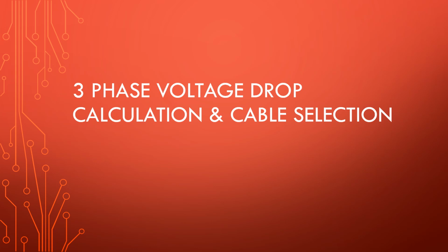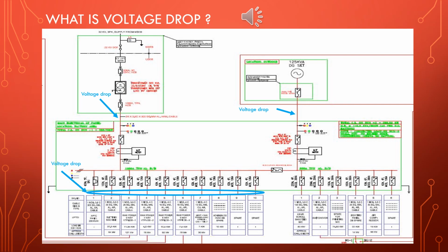Hi engineers, today we will see how to size cable by taking into consideration voltage drop calculation. We will do this with the example of a 3-phase 415-volt low voltage system. First, let us understand what is voltage drop.